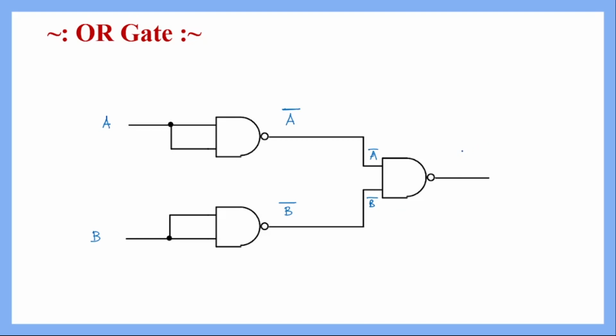So finally the output of this third NAND gate will be a complement as one input and b complement as the other input. First we will perform AND between these two inputs, and then we will perform NOT, and that will complete the NAND operation. So this way we will apply De Morgan's law. a complement and b complement will give us a plus b whole complement, and then we already have another complement, the whole complement, that we need to consider.